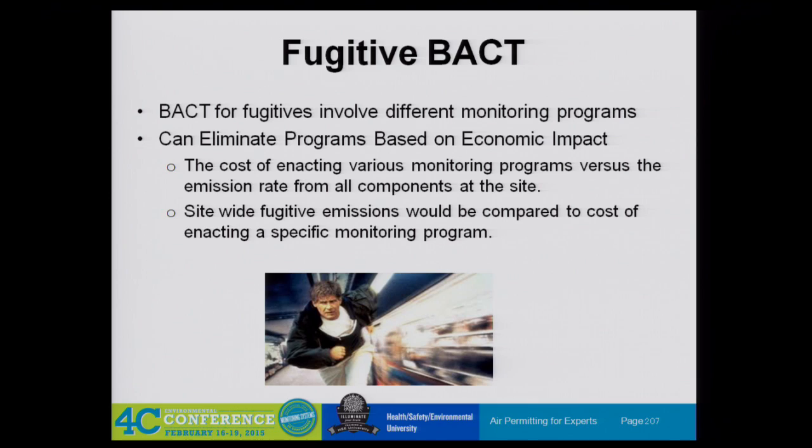programs for the chemical industry, for the SOCMI industry, for the refinery industry, or whatever industry, and all those have slightly different levels of what's a leak rate, what's the inspection frequency, and all those, as a result, have a different level of control associated with them. And what's happened is that the states now are expecting you to evaluate that. What level of control are you proposing to limit your VOC emissions, if VOC is the regulated pollutant that goes over the threshold? That these are modified units.